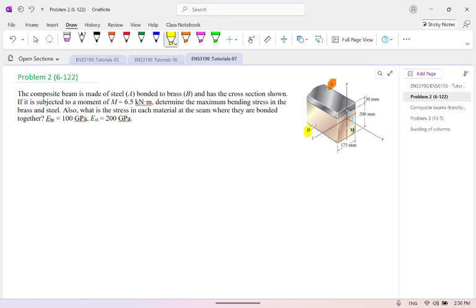Again, we see the question itself. Determine the maximum bending stress. That means sigma max is equal to Mc over I. Again, the c is farthest away. I will write it down again. This is from lecture 6 and tutorial 6. Of course it's the farthest away. But for any location, sigma will be equal to negative My over I. So for this we must get the idea.